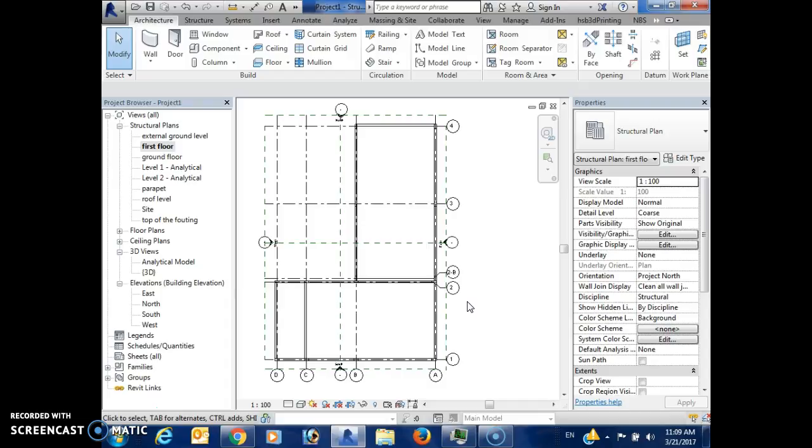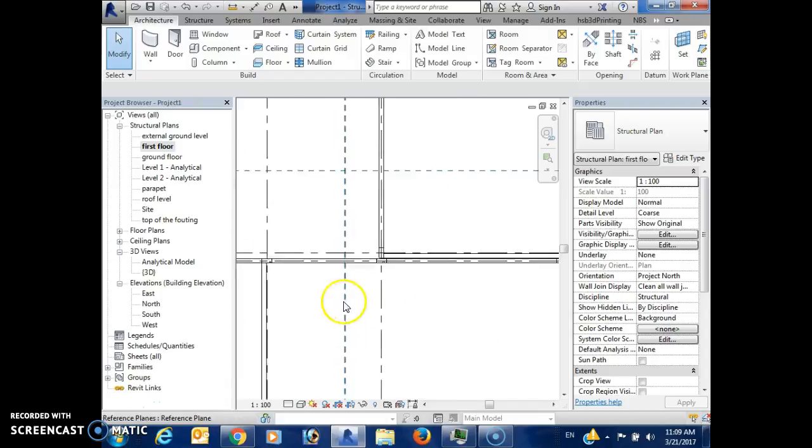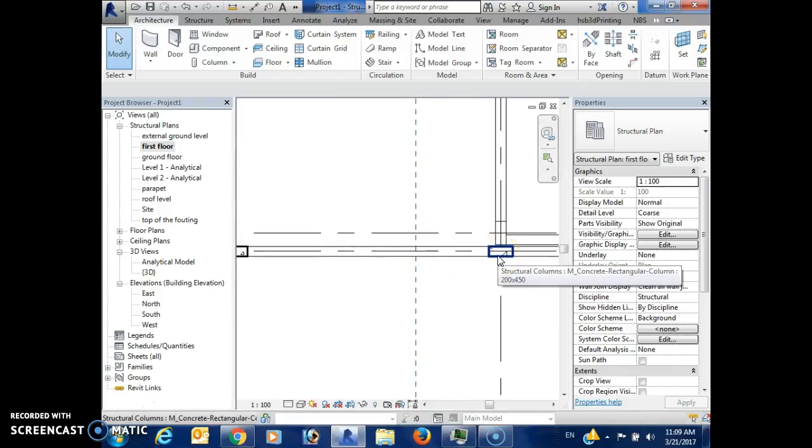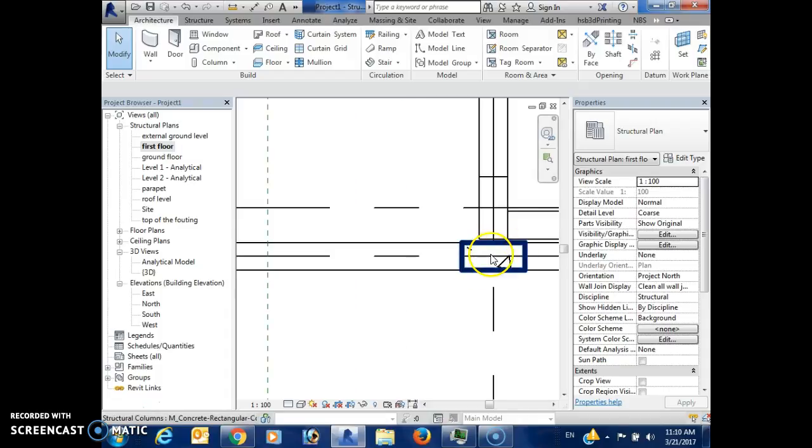The thing is that if we are in the first stages of the project, these elements, the ones that are in section, should be shaded. If we are in another moment of the project, these elements will have the reinforcement instead of the shade. But usually they will never show like this. It will show like this plus the reinforcement, or it will show like shaded.